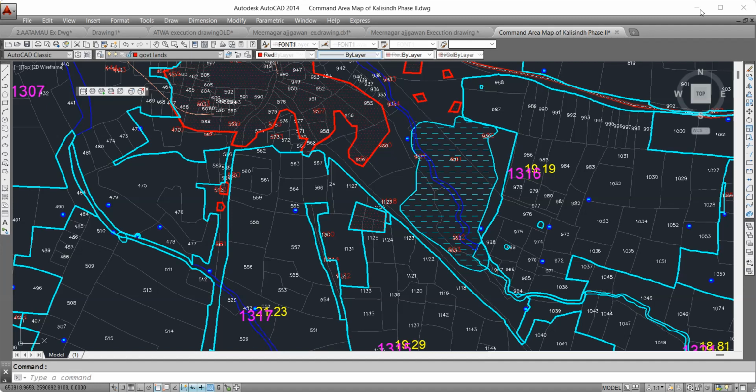First of all, how does the EPANET software work? EPANET computes head loss using the Hazen-Williams formula. Minor losses due to bends and other fittings are also included. Next, operation of the program is very simple and it gives the outputs in the form of nodal pressures and flows.